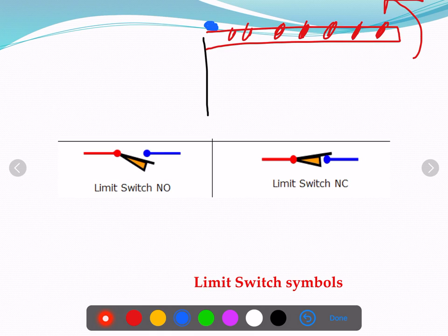Here I make my motor stop after it rotates fully. Now if it's going back, and while it's in the middle it needs to stop because a car is coming, it will open only half of the distance. So you can't take the number of motor rotations as fixed. It has to be flexible. So how to stop and start the motor? By hitting a limit switch. This is an example of a limit switch.